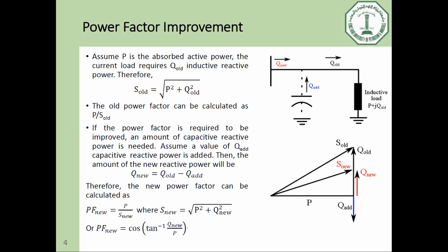Most of our loads are inductive. Lighting loads are inductive. Motors are inductive. Okay, guys? So most of our loads on the grid are inductive. So the power factor in any power station will be lagging, because the reactive power is moving from the generator side to the load side. This is the majority. So we describe the majority case, which is that you have an inductive load and you need to compensate this power factor